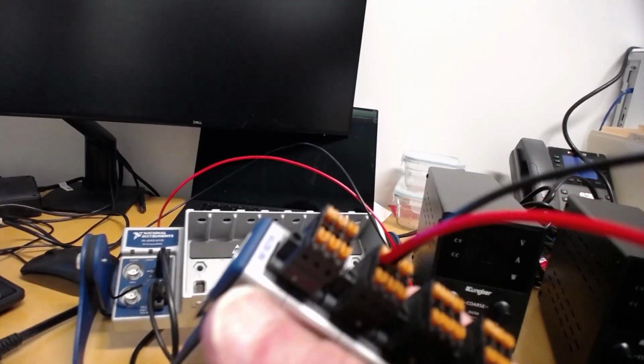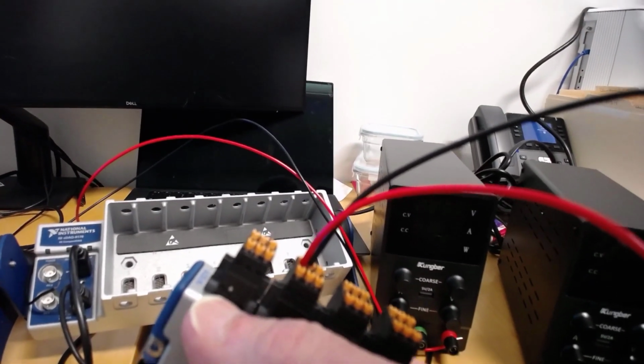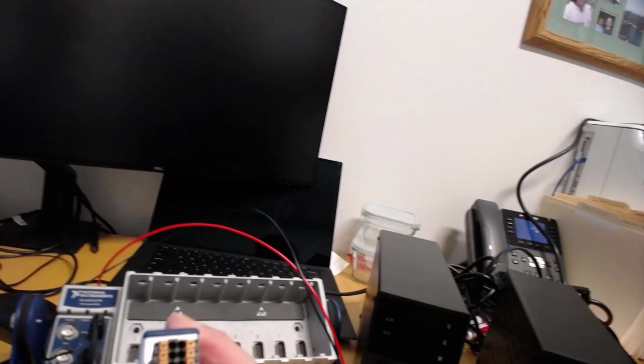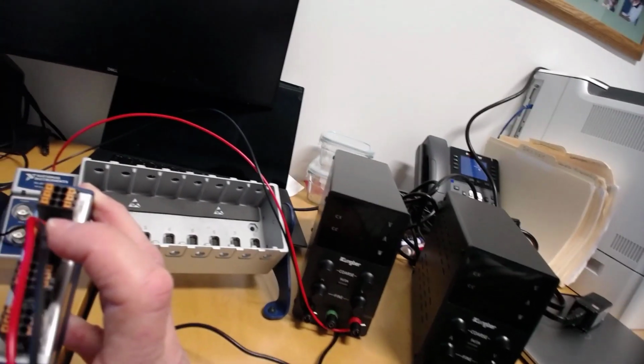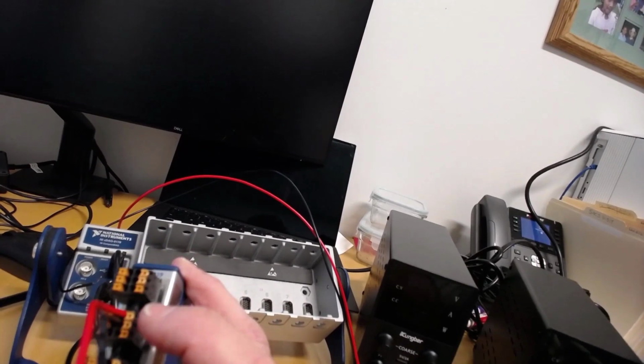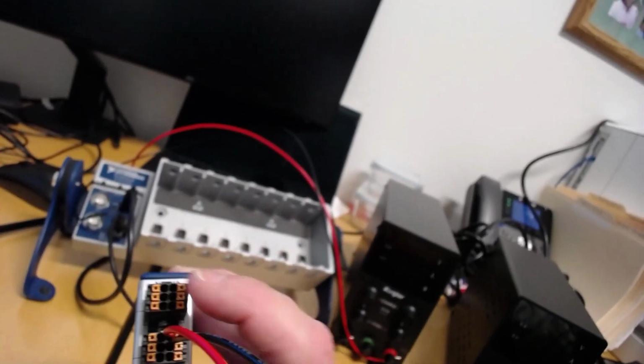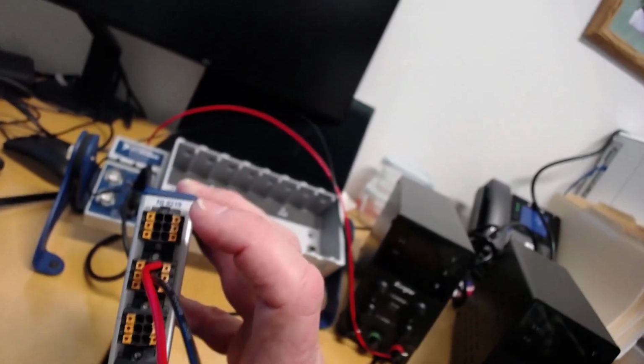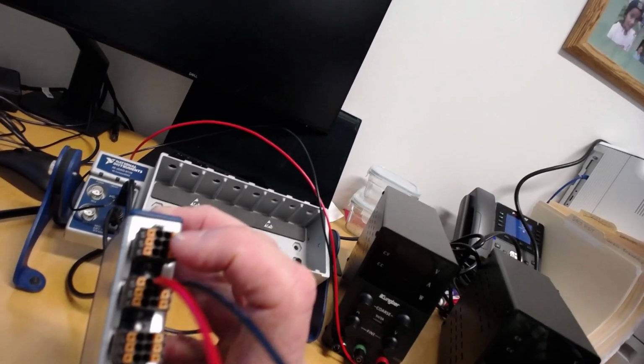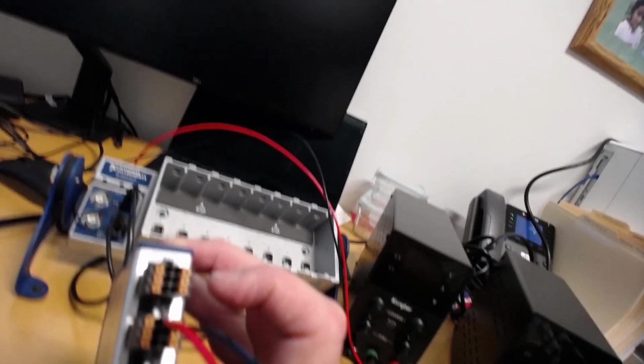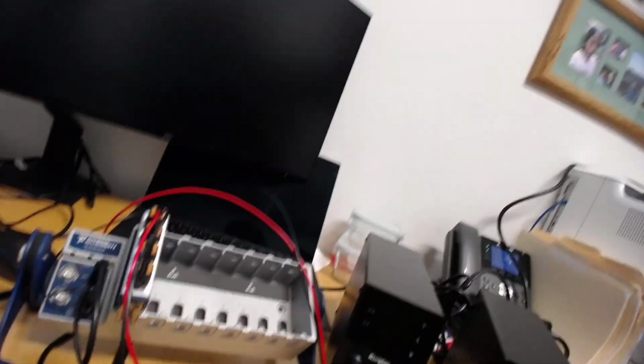If you look on the sides of the module, you'll see numbers. Over here, I see 1, 2, 3, and over on this side, I see 4 and 5. The power supply on the right, I've already wired in right here, and you notice it's in the top two. That's 4 and 5. I'm going to do the same thing with the ones on the top here. One trick: when you insert these, you push it down, put the wire in, and make sure you pull on the wire to make sure that it's in good. So I'm going to put this module back in the rack, put the other wire in, and then we'll start the program.